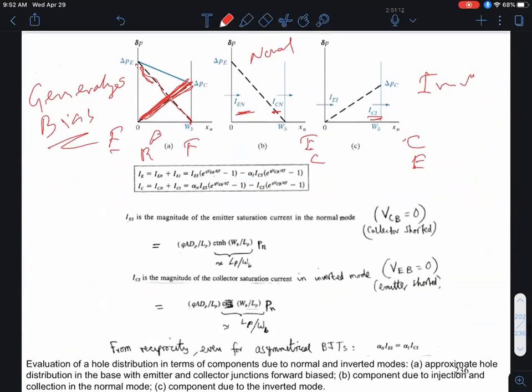However, in digital circuits, in the past, at least when people used BJTs for digital circuits, sometimes you have to invert the thing when you want to turn the transistor off, et cetera. So anyway, in this generalized mode, you can write down the current as a linear combination of the normal mode of current plus the inverted mode. So that's my normal mode component, that's my diode expression.